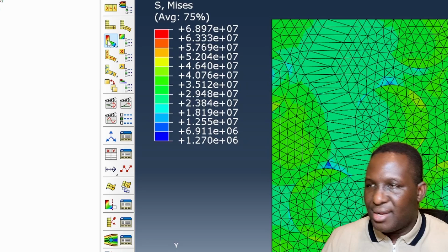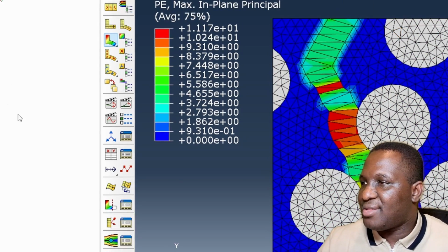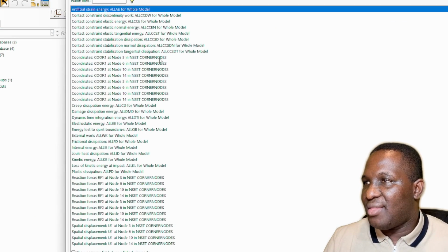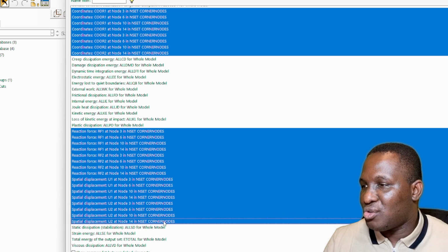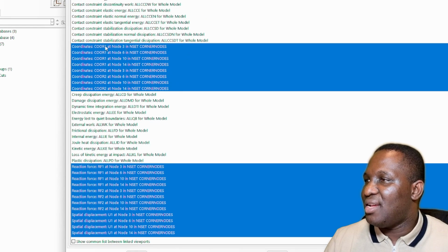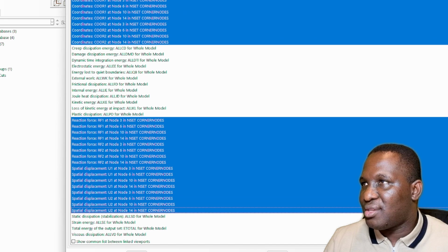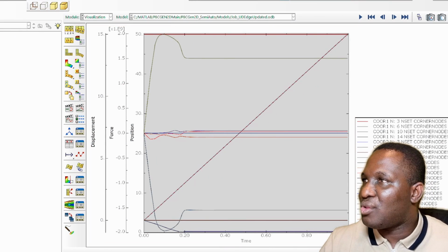The next thing that we need to do here is to see if we can generate the stress strain data from this. So let's look at the tensile case. So what do we do with the tensile case? You just use this button, and we're operating on the history output, and then press down shift control, and then scroll down, still pressing down control. So we select all those variables that we asked for, the coordinate system, the reaction force, and displacement, and then we just plot it. So obviously that information gets plotted this way, so don't worry about it.